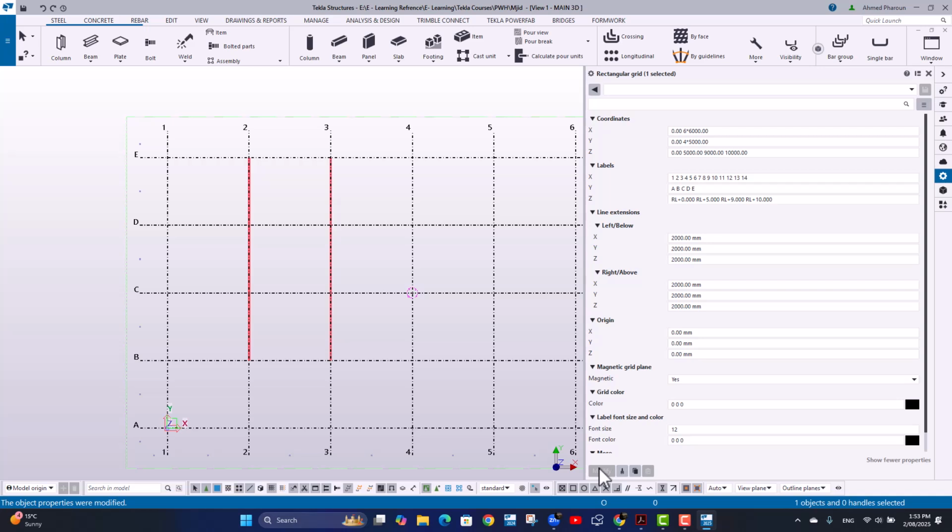They are located in between the grids. So they will shrink from the start and the end, but in the intermediate they will crash or clash into each other. So it's important to use the magnetic grid line only if you decide to use it with a lot of thinking before and checking after.